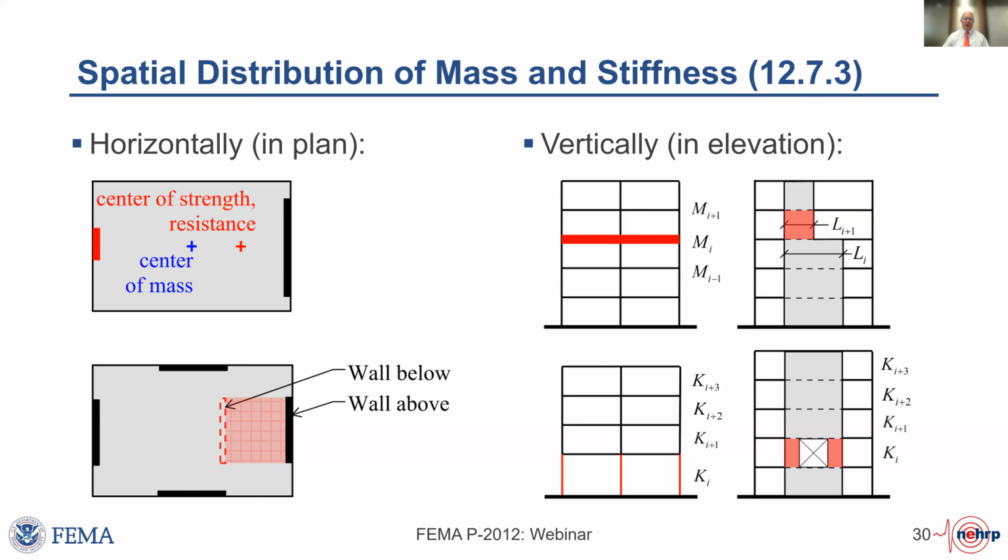So for instance, you see that you have to think about where masses are greater at one story than at others, maybe where stories are taller, where the system changes so it's non-uniform. Perhaps there's weaknesses introduced because of the reality of having door openings or something like that. But the code requires that our mathematical model has to consider these aspects of the configuration.